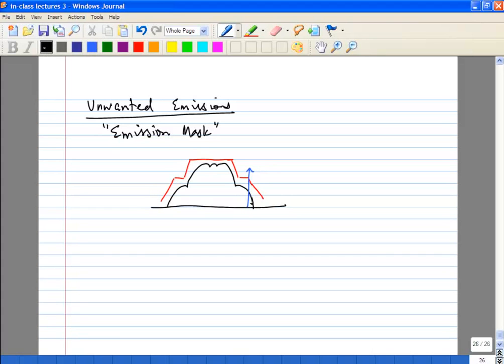That's your emission mask. Then you have something called ACP, or adjacent channel power. You are trying to transmit in a particular channel and you shouldn't damage the guy who's transmitting right next to you, because that is where typically you will have most issues. The person who's closest, remember, you can look at the power going down as a function of frequency. The guy right next to you will probably have the most problems. So they have specs on how much you can transmit right in the adjacent channel. And usually the power levels are still high enough that you will be limited more by linearity rather than noise.